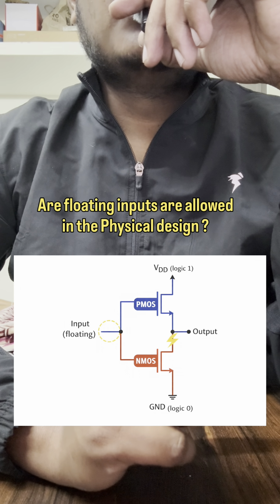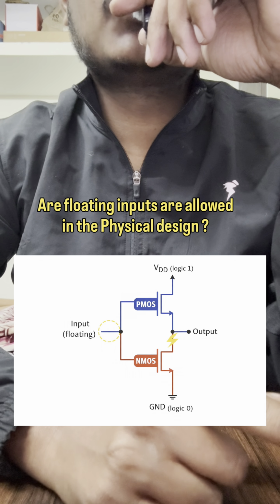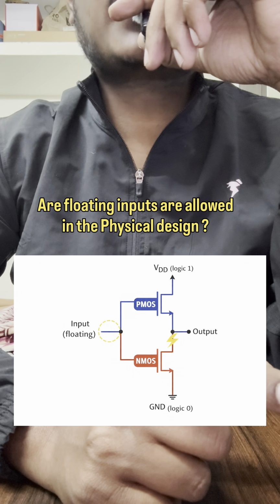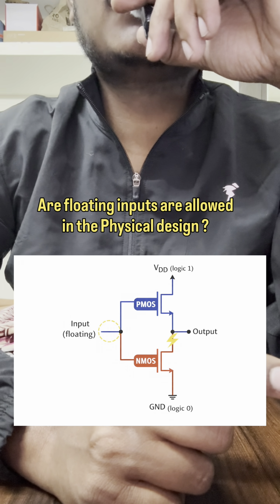If both transistors are partially on, a direct current path is created from VDD through the PMOS, then through the NMOS to the ground. This is called short circuit current. This increases the static power consumption and it can cause heating and reliability problems.